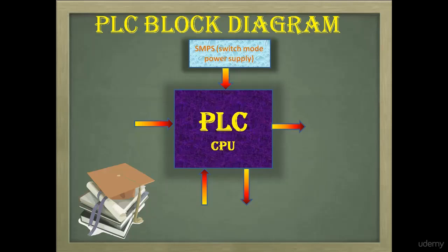For the programming of a PLC, there must be a computer or laptop. By this, we can easily transfer the program to the PLC or to the PC. Transferring the program from PC to PLC is called downloading, and from PLC to PC is called uploading. For downloading or uploading the program, there must be a communication cable for connecting the PC and PLC. The communication cable can vary according to the PLC model or company. For this PLC, Micrologix 1000, we will use the PM02 cable.